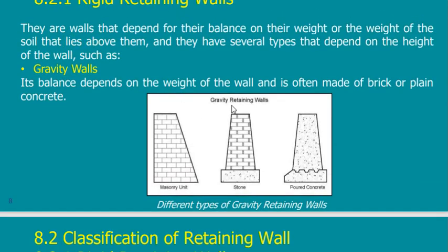So a gravity retaining wall means walls that are not very high, and at the same time they are bulky, because they work under gravity. It means that this wall does not carry tension. It only carries compression. When I say gravity retaining wall, it means that it's affected by gravity. Gravity is always downward, so it means that the wall is always in compression.